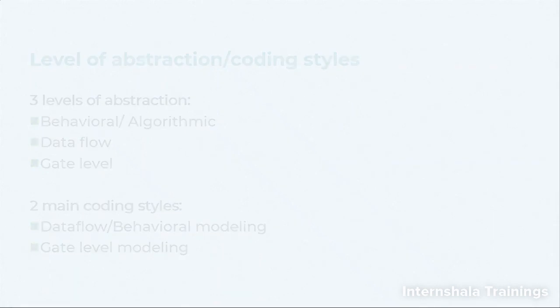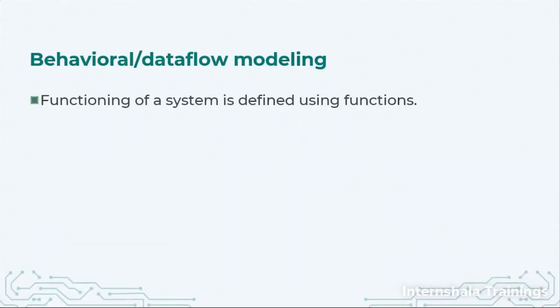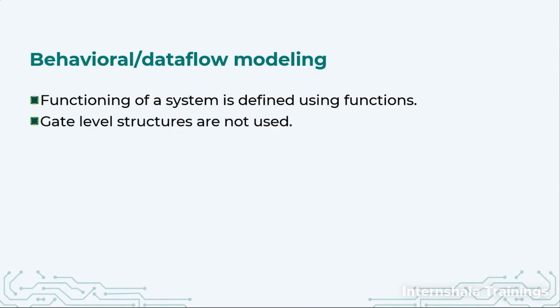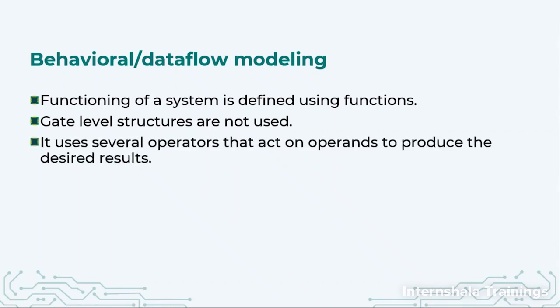When we talk about Dataflow modeling, here we are basically defining the functionality of the system using some functions. Here we do not define any gate level structure or gate level relation in a single line. We are going to use several operators that act on the given operands and produce the desired result.